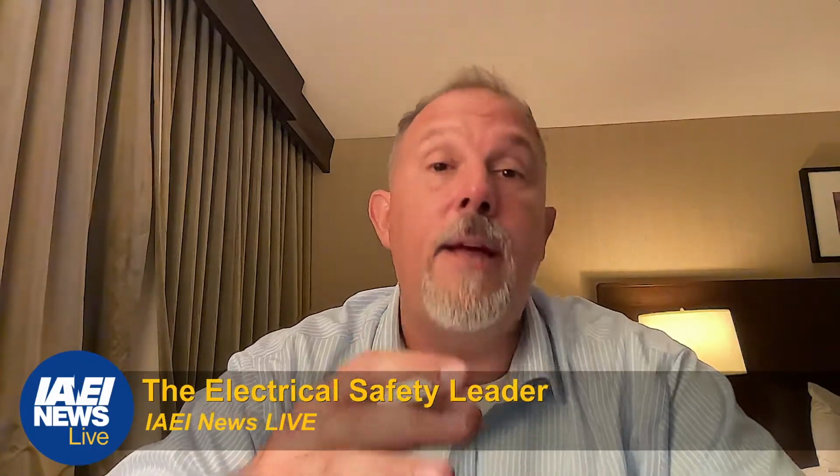And remember, you've got copper core, you've got aluminum, you have temperature rated, you have high efficiency transformers. You have K-factor transformers that deal with the harmonic currents. There are just so many different types of transformers and different applications where you might use one over another. A lot of that is outside of the NEC requirements, but it's important to understand. And work with your manufacturer, please.